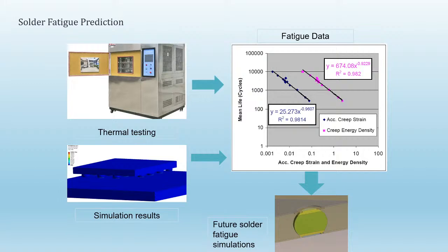Companies are already doing lots and lots of environmental testing. So this is a machine, an oven, that you put your electronics in. It'll cycle the temperature up and down for a week or a month, depending on how extensive your testing needs to be. And you know how long it takes. There will be a point that says, okay, my chip has failed after a certain number of cycles.